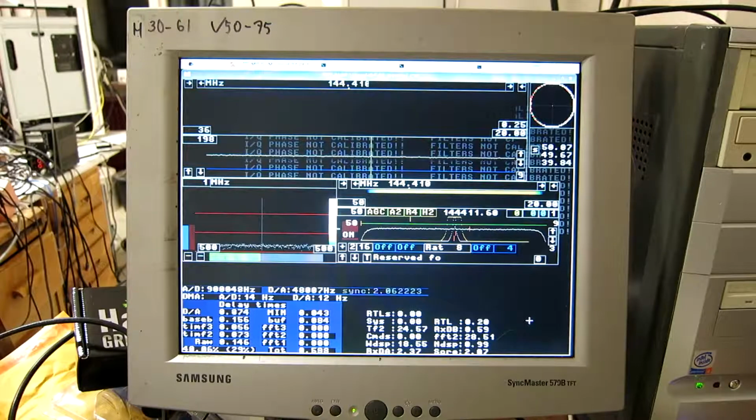But I have not yet set the optimum parameters for visibility in the main waterfall. That's not necessary. I can be satisfied with only the baseband waterfall, and then I don't need the second FFT, and that saves a lot of resources.